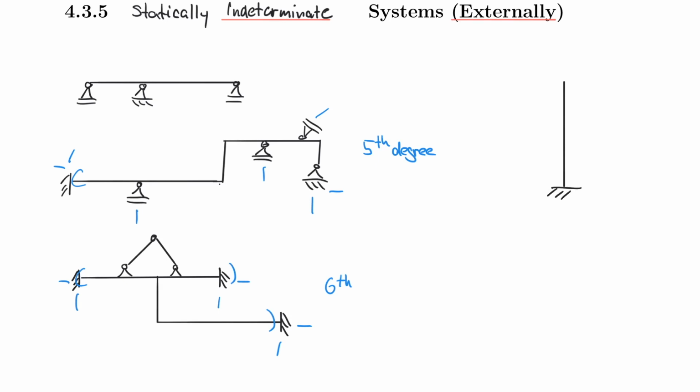So this, of course, you know, is statically determinate because you can calculate it. And now to explain to you internal statical indeterminacy, I want you to consider the following. So I'm going to weld something to this cantilever beam. So this is a rigid frame. Think of it as being made from metal. And as of right now, this is a completely statically determinate system because everything is free to move and there's no restriction. But as soon as I come in and weld this together, so let's say I weld something on here and I rigidly connect this,